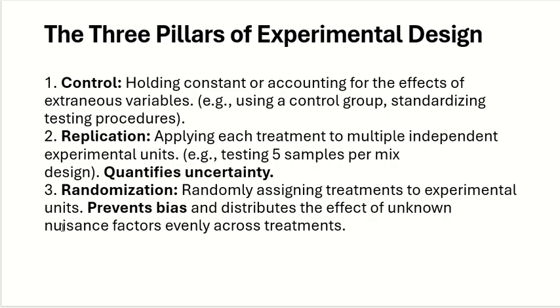What we found is that the fibers actually need a specific cement content, the percentage, the ratio, to give you an advantage over the control sample. Otherwise, the fibers can actually reduce your strength. We would not find this until we had the control group.